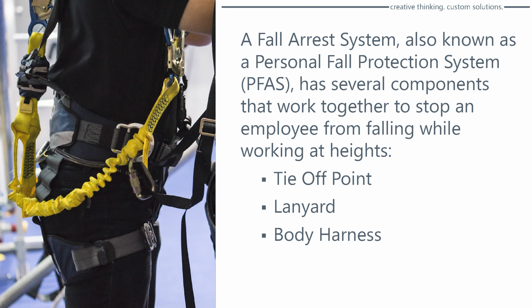Well, the fall arrest system, 3 components. You got your tie-off point, super important, lanyard, of course, and body harness. Let me ask you a question, if I can. Think about how often should these items be inspected? They should be at least every time before you use them. All right?